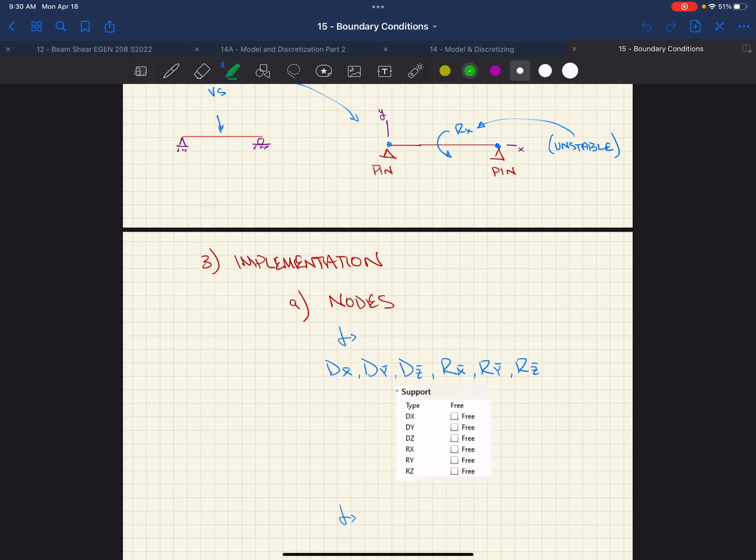You just said on the windward side, so load every side with the wind. I gave you a wind load that was a pressure based on the windward side loading. Usually, depending on what chapter you use and you're developing those loads, you will get a leeward and windward pressure that you would apply to your building. I'm just saying that you only have a windward pressure. So when you're looking at wind coming from the east, hitting this broadside, you've got 30 PSI. And from the north, 30 PSI. West, south, same thing. Yes, it's all four sides.